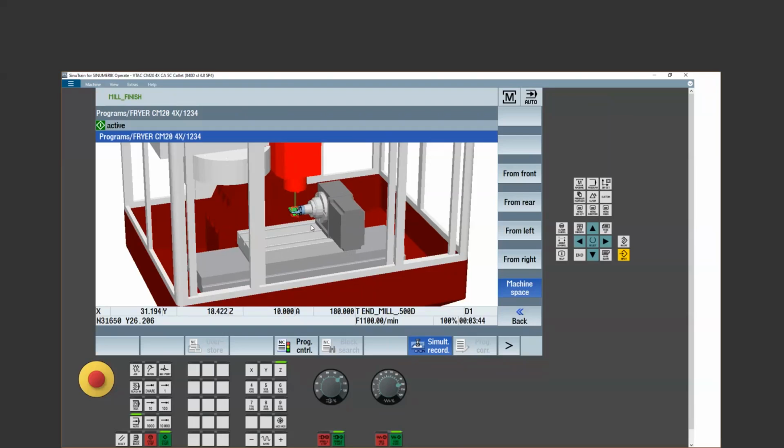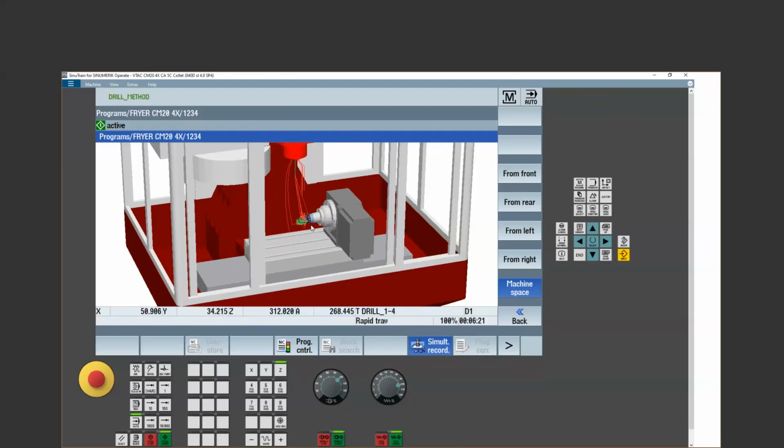Now, there are a few areas that it's not going to know. Certainly, it's not going to know how long my tool change is. So that's probably about the largest area where I would see any discrepancies. But acceleration, deceleration, speed of my rotaries, all of that is 100% known by this digital twin.